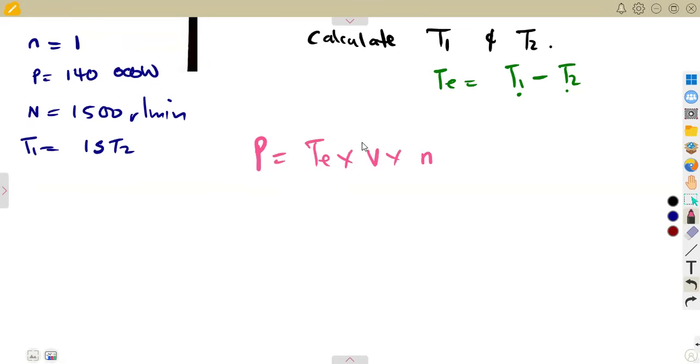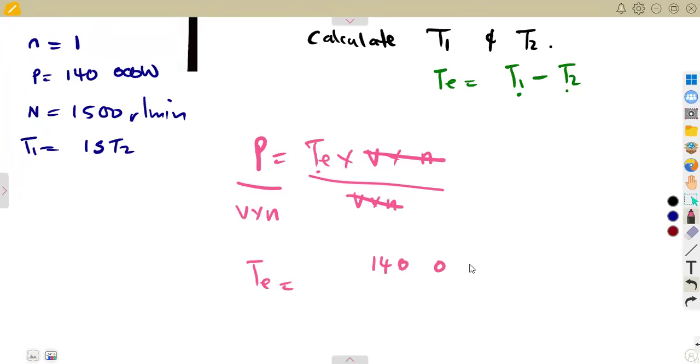That's how you're going to calculate our power there. So meaning to say, to have this effective tension, you're going to calculate by the velocity times the number of V belts. All right, that's the effective tension that we want, where the power is given. The power is 140, so this is 140,000 watts, everything over the velocity. Remember, we are given the speed.